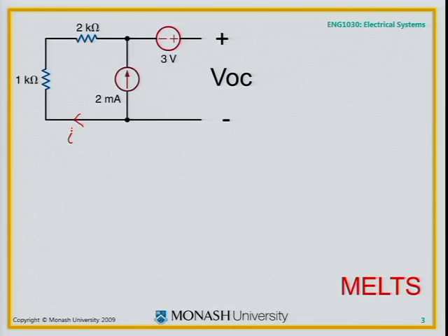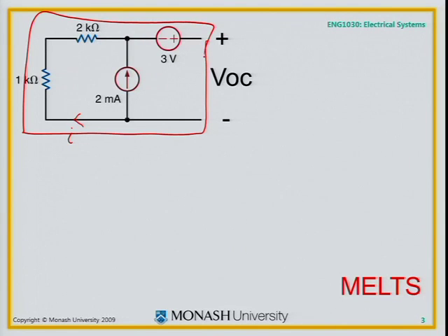One thing, I could do Kirchhoff's voltage law around the outer loop. That's maybe what I'll do. We used to go in clockwise, so we could do this. Go here, here, here, and back to there. What does that give us starting here? Well, I would have VOC, plus minus in that direction. The voltage I'm looking for, VOC.